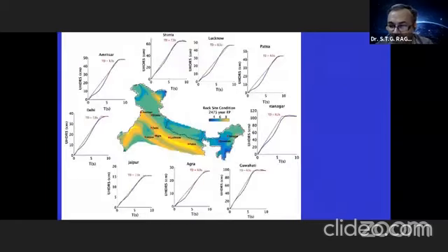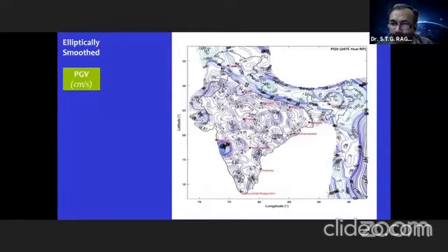And now these are the displacement response spectra. So we have constructed them for various cities in our country. Most of you would have seen the pseudo spectral acceleration spectra, which is given in the IS code. So these are the displacement response spectra, how they look actually. You can see the period where suddenly two straight lines are there, where the slope changes. It varies from place to place. In India, somewhere you can say 7 seconds, 8 seconds in the Ganga basin, whereas in the Himalayas and other places, this turns out to be somewhere around 4 seconds.